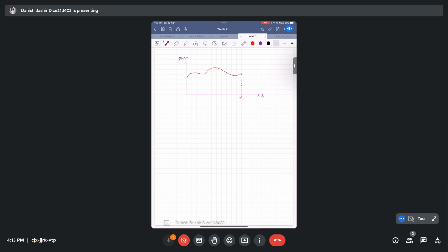So let us assume at any instant of time we cut a very small strip of this forcing function such that it makes an impulse response function. That is, the area of this strip is unity. So at any time tau, it was having some value, it will be p of tau.